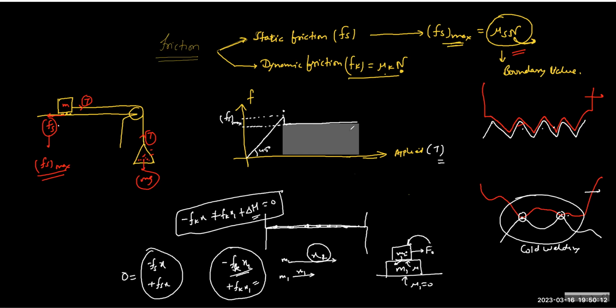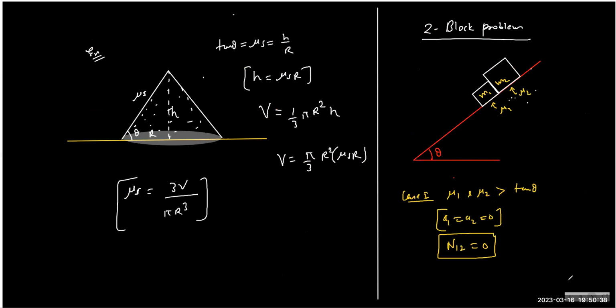You have to check actually. So you will assume the friction, you will solve the FBD, you will get the F answer, and then you check: is my F, which I calculated, more than limiting or less than limiting? Is this clear what I'm saying? Yes, sir. That's what you're supposed to check. So now if you go back to this problem, let me go to the next problem.